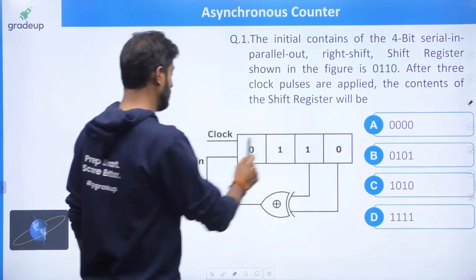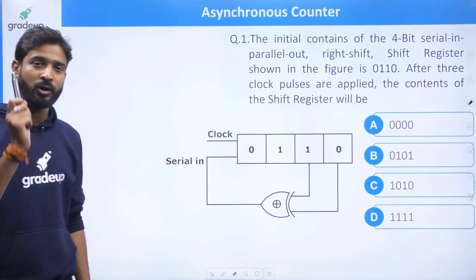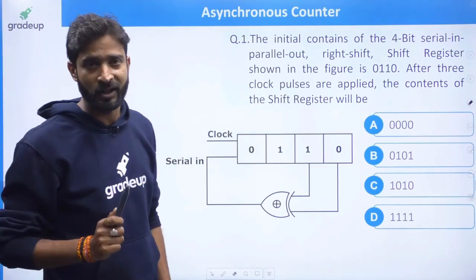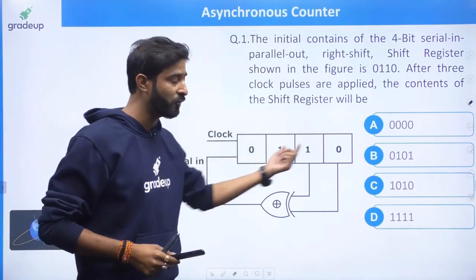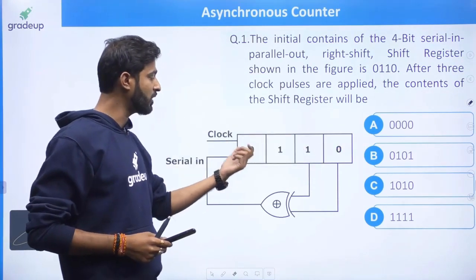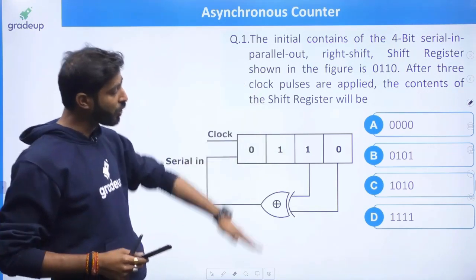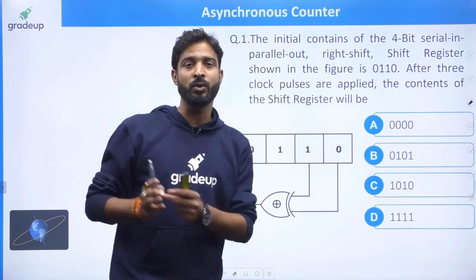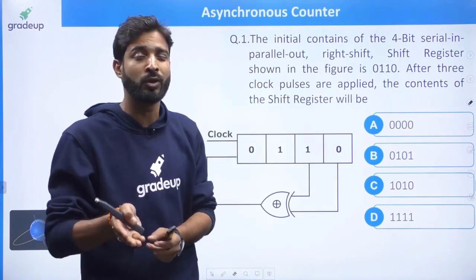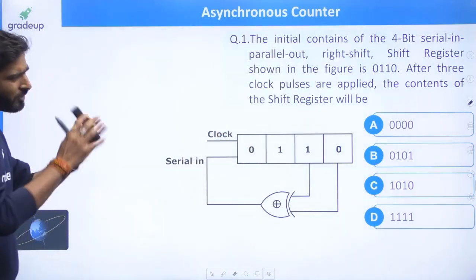And yes, my dear friend, the shift register is a synchronous device. Synchronous device means all the flip-flops, generally D flip-flops, are connected with the same clock. It means whenever the clock is applied, all the flip-flops work simultaneously, and the data present at the input of a flip-flop will be directly moved to the output of that flip-flop. That is the basic thing.